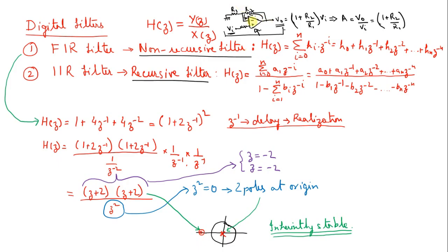If you see over here, at the non-inverting terminal, we are having a feedback loop. Now this is called a closed loop system. Now if we are not taking any output from the op amp and there was no R2 over here and it was blank, then it would have been an open loop configuration of the amplifier.